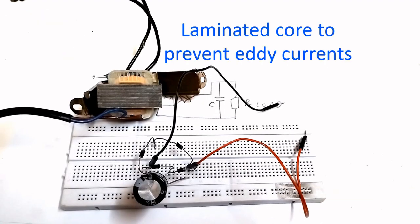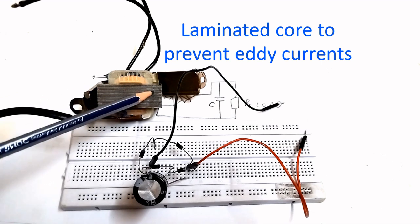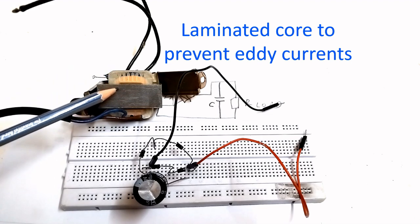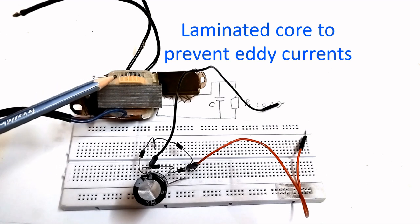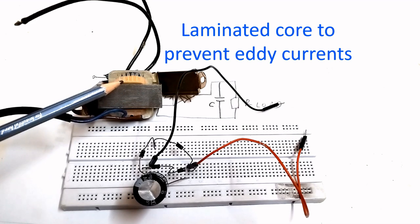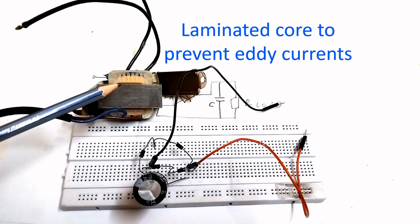I have just removed part of the cover of the transformer just to show the laminated core. You can see that this core is made of several laminated sheets, and the lamination is needed to prevent eddy currents. The core will have eddy currents, will heat up the core, and that can be prevented by using a laminated core. And when eddy currents are there, that will cause generation of heat and loss of energy, so that the efficiency of the transformer in converting the power will be reduced if you use core without lamination. Core with lamination will improve the efficiency of the transformer.